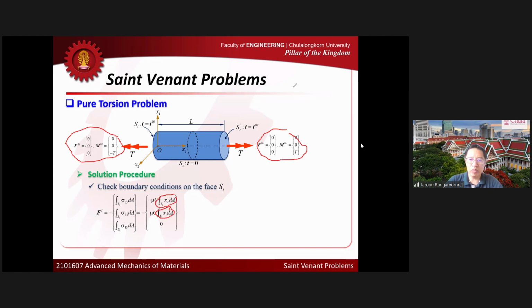So now I end up with what? I end up with 0 net forces in all directions, right? And that should be clear that it's identical to what we prescribe there. So FL here is exactly the same as FL0 from the traction. So now I can say that at the left end, the net force conditions are satisfied automatically. It doesn't matter what the value of C is.